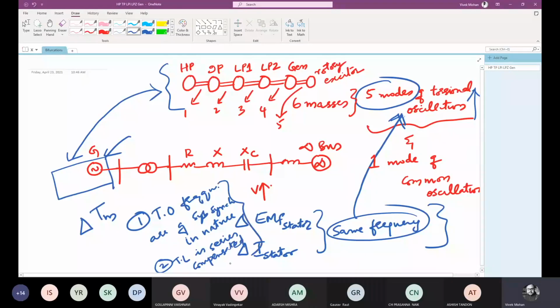So in this condition, we observe that the currents generated in the grid because of the mechanical disturbance in the multimass system affecting the momentary rotor speed, these currents have frequencies near to the natural torsional frequency of oscillation, and this will enhance the amplitude of torsional oscillation, and it may go unstable. The shafts may break, or the twist of the shaft may be unbounded. Now, this phenomenon is known as subsynchronous resonance.